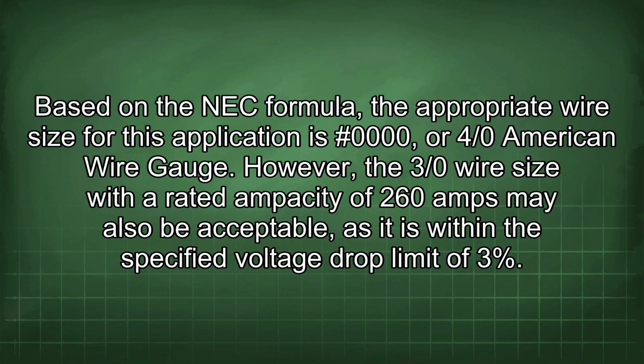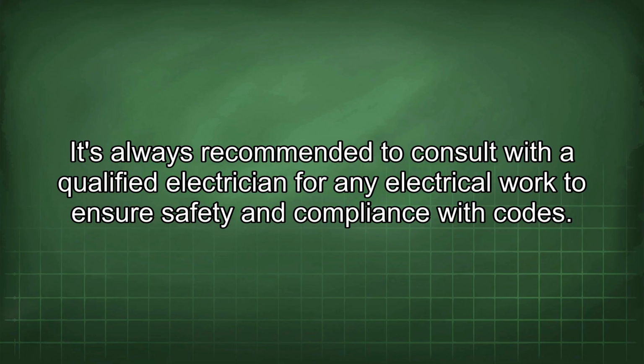However, the 3/0 wire size with a rated ampacity of 260 amps may also be acceptable, as it is within the specified voltage drop limit of 3%. It's always recommended to consult with a qualified electrician for any electrical work to ensure safety and compliance with codes.